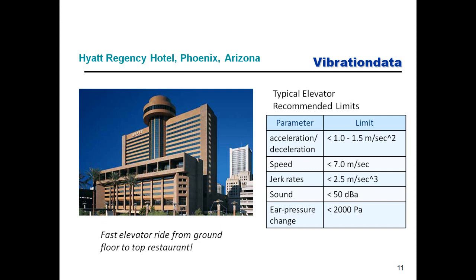There's also something called jerk. Jerk is the time derivative of acceleration. We don't usually deal with jerk, but that parameter does exist. And the jerk rate is less than 2.5 meters per second cubed. So our bodies do detect jerk. Our bodies do not like to be jerked around. And of course our bodies also can detect acceleration because force equals mass times acceleration. There's also a requirement for the sound level and the ear pressure change shown there. So all of those are important for the passengers on the elevator.